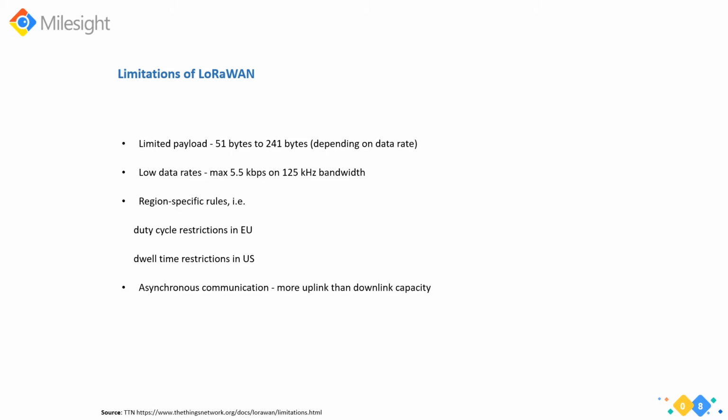And you can also enable the adaptive data rate, ADR, mechanism. The network will be able to automatically optimize your data rate and instruct the end device to change the spreading factor. And most of the time, 90% of the traffic is uplink from the end device towards the network, and downlink is typically limited.